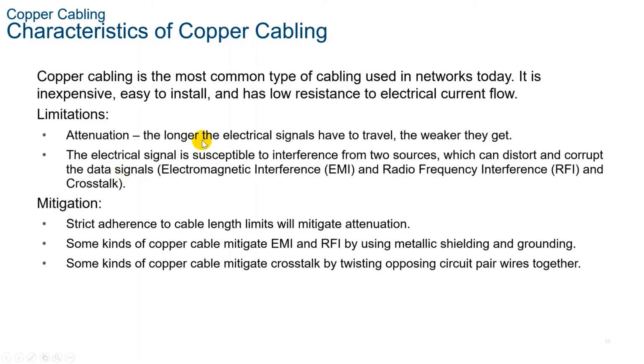So next is crosstalk. What is crosstalk? Crosstalk is a disturbance caused by the electric or magnetic fields of a signal on one wire to the signal in an adjacent wire. In telephone circuits, crosstalk can result in hearing part of another voice conversation from an adjacent circuit. Specifically, when an electrical current flows through a wire, it creates a small circular magnetic field around the wire, which can be picked up by the adjacent wire. So that's crosstalk.